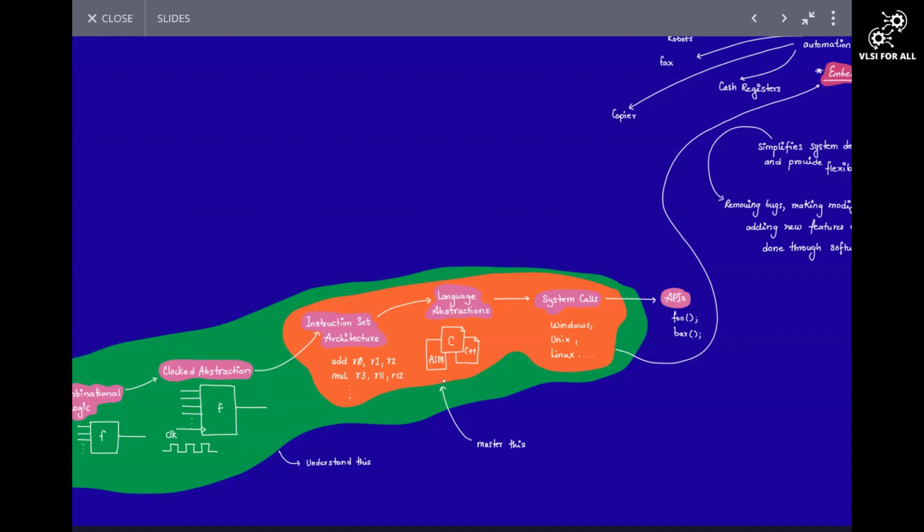But you are not just writing software, right? You're writing your software consciously. And also in some cases, which I discussed at the end, you're calibrating a sensor. You're writing some values into the registers of that sensor. So you're operating with a sensor at the end of the day. Let's say an ADC, right? Sometimes you need to convert analog to digital data. In that case, you need to use that ADC. You need to know the working of that ADC. Only then will you be able to program its registers correctly to get the values correctly.